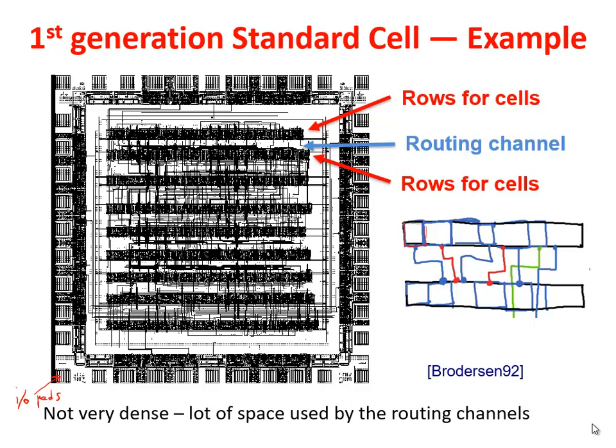So the standard cells, the cells in the library, are done in a way to have a layout which is quite regular. Each cell has the same height and different width depending on the complexity of the cell, so that you can build a row together, as in that design, as a sort of Lego structure.